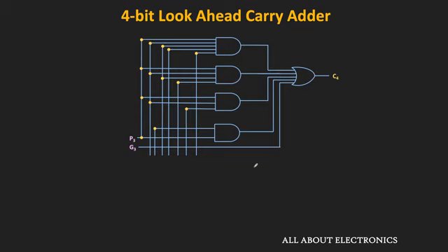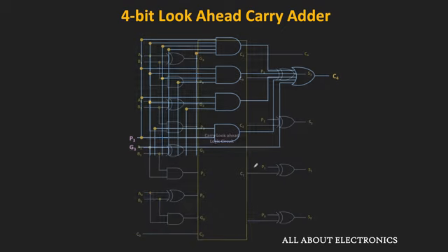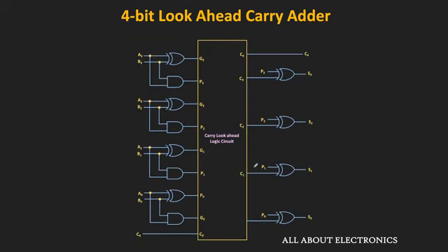Moreover, as the number of inputs of the logic gate increases, the speed of the logic gate will also reduce. But of course, here for simplicity we are assuming that irrespective of the number of inputs of the logic gate, the propagation delay of all logic gates is the same. But actually, as the number of inputs increases, it also affects the propagation delay. So in short, in this carry look-ahead adder, as the number of bits increases, the complexity and the cost of design will also increase.